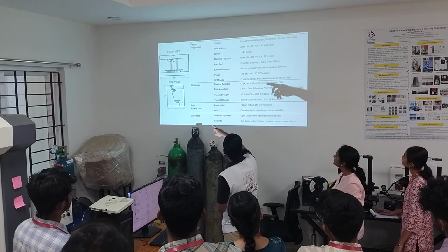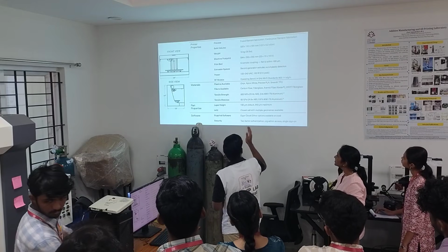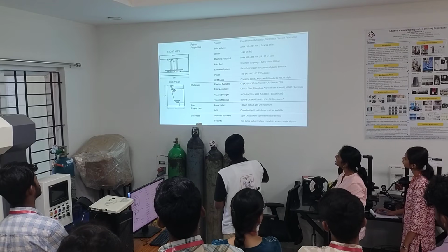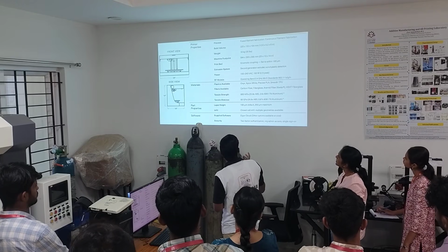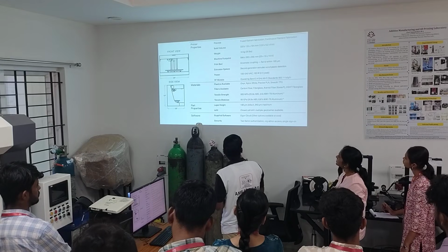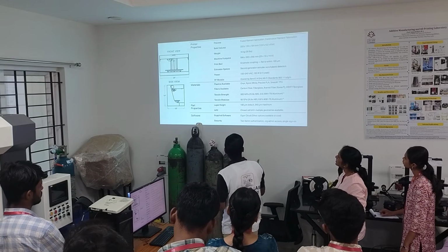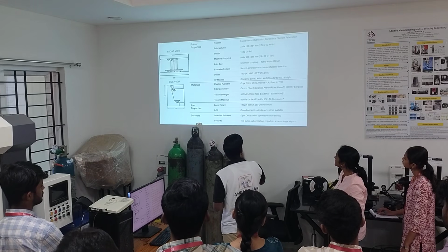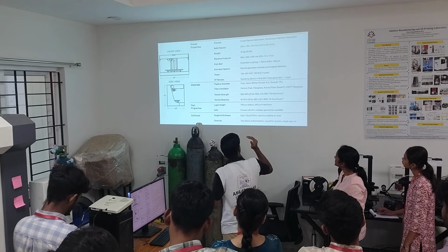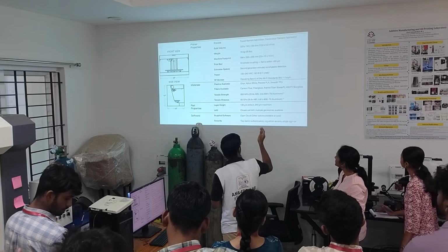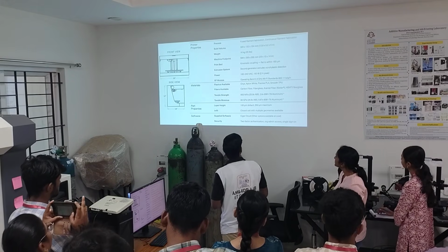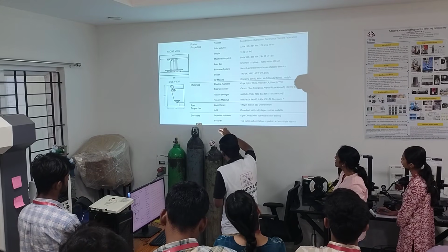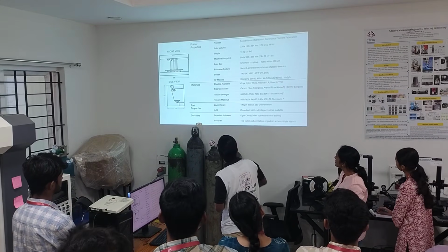And the materials which we are using can be onyx, nylon, PLA. They have their own. All these materials are their proprietary materials, and onyx is one of their own developed materials, which is very much better compared to ABS also. Fibers, we have carbon fiber, fiberglass, aramid fibers, high strength high temperature fiberglass, also normal fiberglass. So this kind of fibers as well as the plastic can be used here. Plastic basically means the matrix material.